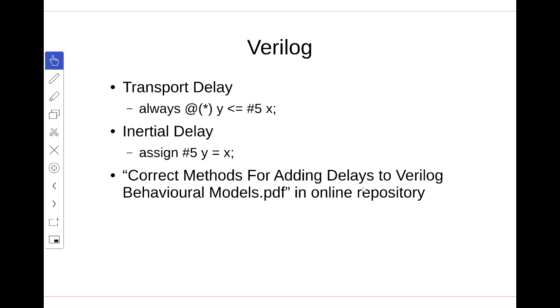Verilog gives you so many ways of introducing what look like delays. It's very hard to know that you're doing it the right way without lots of experience. So I'm basically telling you either do it this way or this way and no other way. This article shows you that almost any other way you find is not going to work properly in all situations. If you don't care, then just memorise this for transport and that for inertial. If you do care, read this article and you should find it quite fascinating.